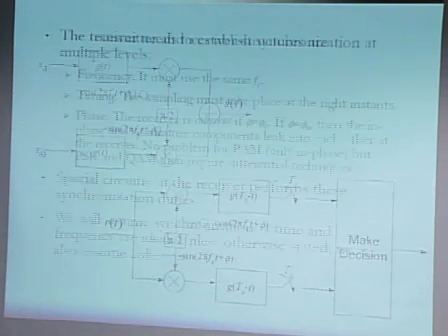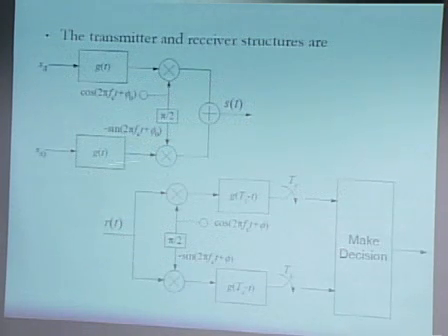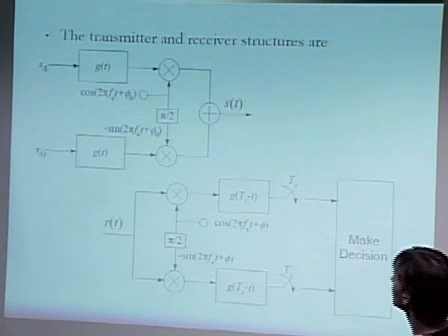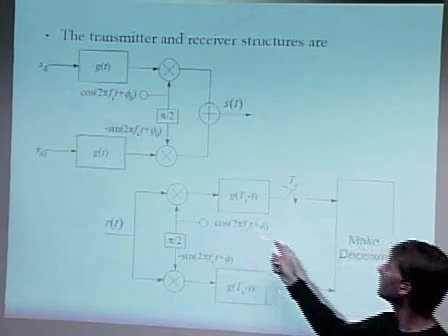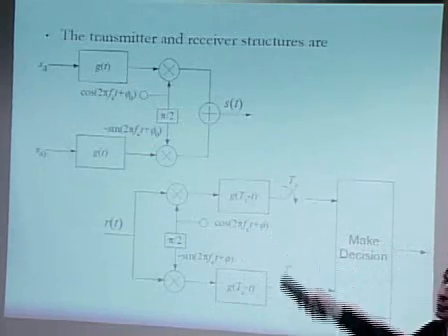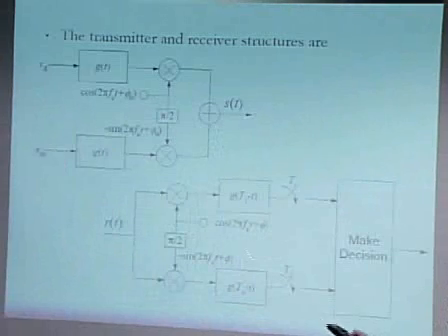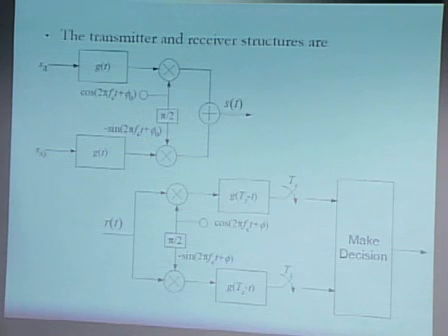And we spent a couple of minutes here talking about synchronization. So remember, this is the structure of the transmitter and the receiver that we derived. And synchronization entails making sure that the oscillator here, the receiver, at frequency FC, has the same FC that is being used at the oscillator of the transmitter, right? If these are different, this frequency difference would integrate into a phase difference that would distort the information.